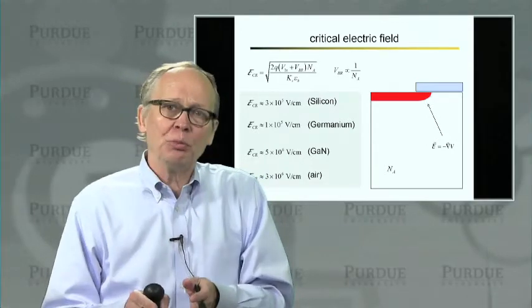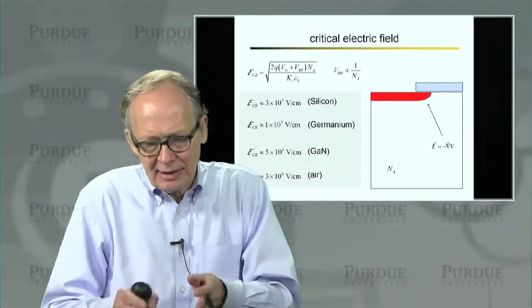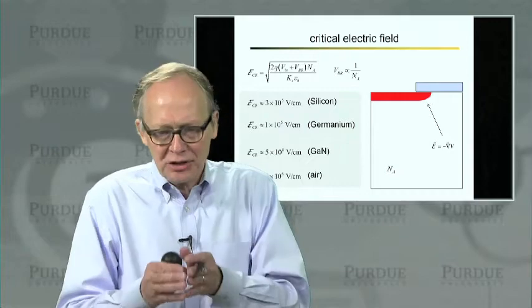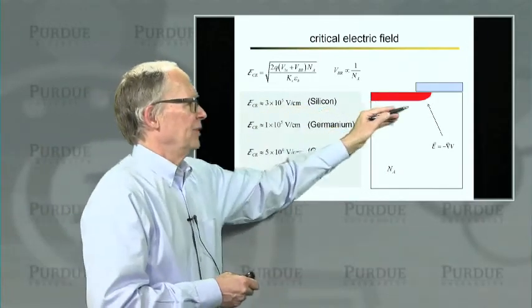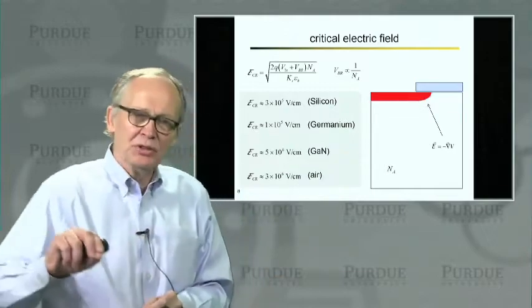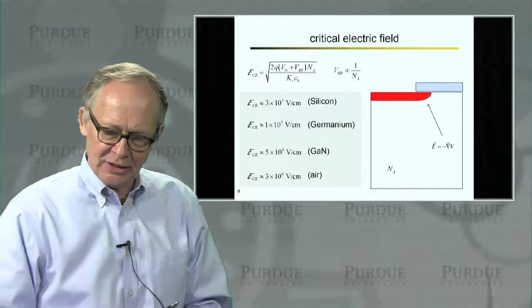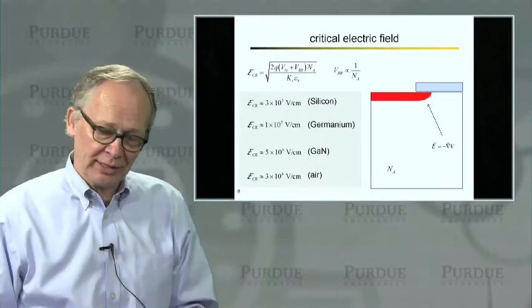You introduce dopants, either by diffusion or ion implantation. You heat up the semiconductor and let them diffuse in or undo the damage of the ion implantation, and they move. And there will be a planar junction, and there will be a curvature as it diffuses underneath the SiO2 that was defining where we're making the p-n junction. Now here we need to remember something from 311.